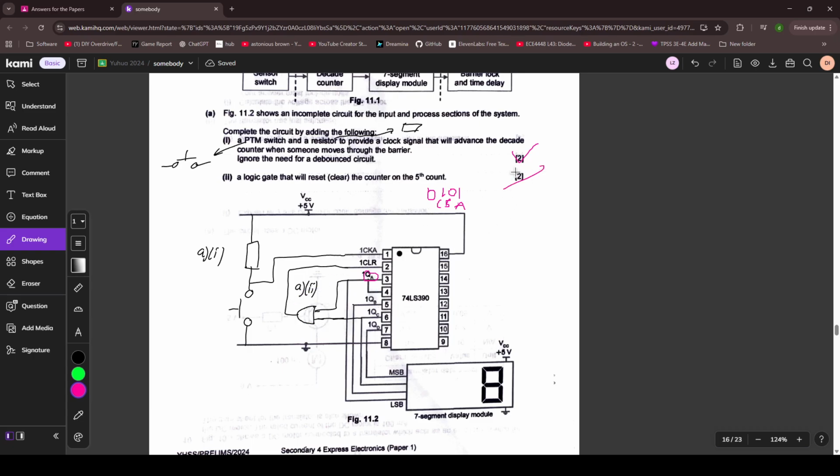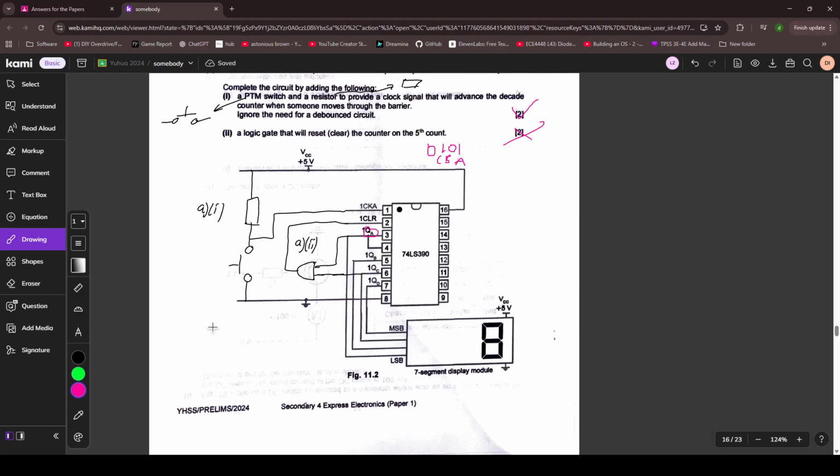You get 0. The reason why is, right now, let me just simplify, what you have is A, B, C, and then you just have an AND gate here, and then your output lah. This works for some cases. Just to verify it, let me make clear what we are trying to do here. When CBA is 101, the output of this circuit here must be 1. Okay? So let's just try some values for the heck of it.